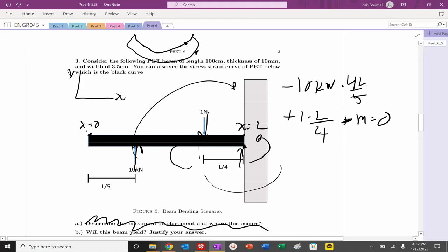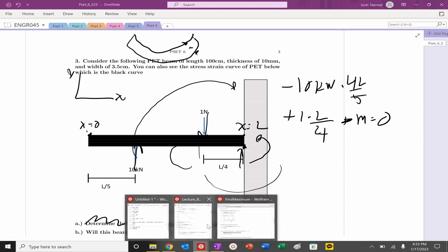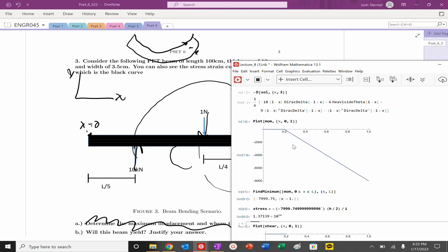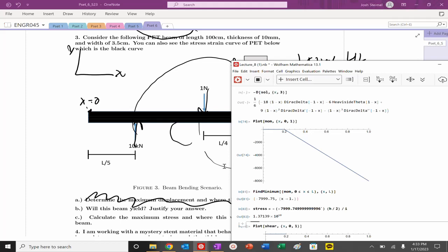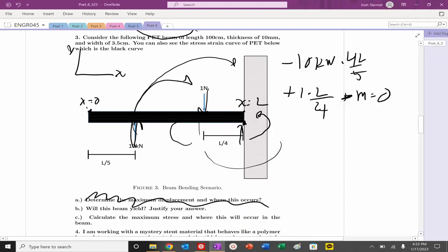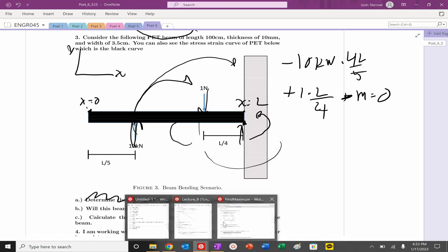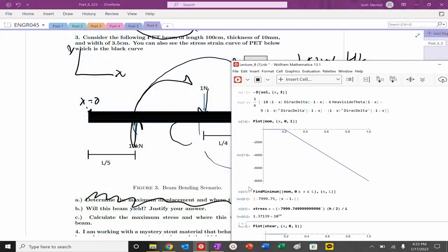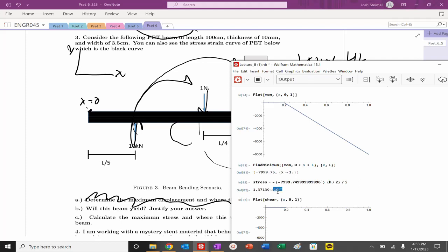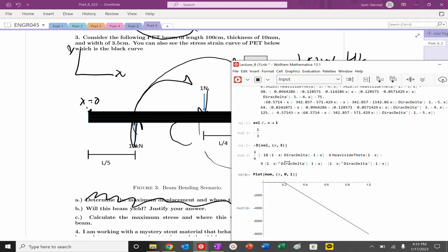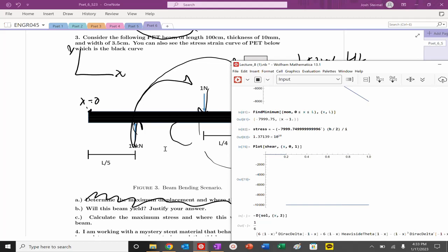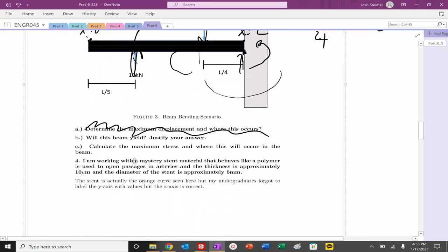And we actually picked the positive y/2. This has to do with a change of notation. When you think about the moments, and especially your definition of positive or negative moment, and considering that the beam is essentially going like this in the clockwise direction, actually it should be negative, but it's the way the definition of the moment occurs. So the top of the beam should have a negative stress. So we actually have to change our definition of our moment. But again, you can calculate that out and justify that.